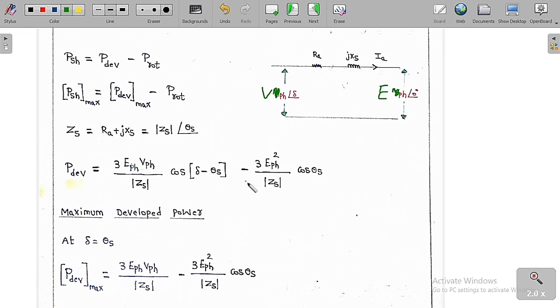So this is the equation that you are going to get if you want to know the electrical power, or you can say the mechanical power developed. I hope you have remembered this formula. Basically, same thing I have already told you, the basic equation. Listen carefully. The amount of electrical power developed is nothing but the complex power S is equal to root 3 into EL into IA conjugate.